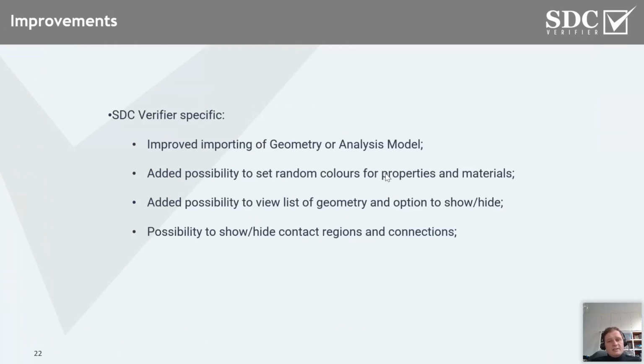For SDC Verifier standalone specifically, a lot of performance improvements and graphical improvements have been done. Among the main ones is the improved import of geometry or analysis models. We can import any kind of DWG, DXF, STEP files, etc. for the geometry, as well as analysis models from Ansys, Femap, Abaqus, other interfaces, dot files, and so on.